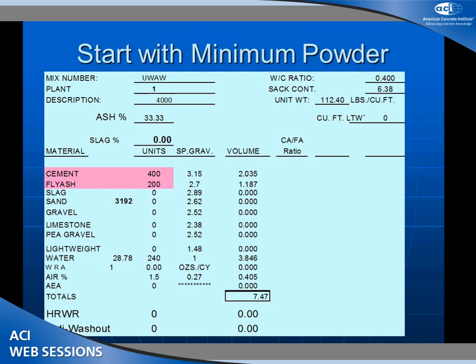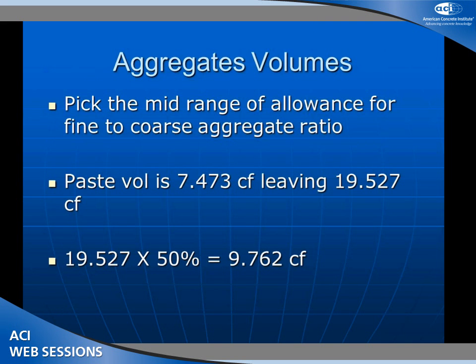So knowing what we know, we've got 600 pounds. Specification typically allows 33 to 35% ash replacement. Because of the reduction in water the fly ash brings, we're going to be able to bring our water demand down to about 240 pounds, or just a little bit under 29 gallons. Underwater, we don't need air, obviously, so we've got these design parameters.